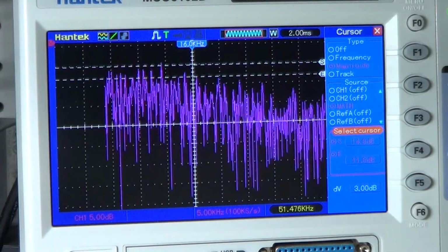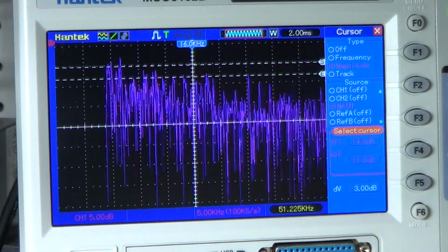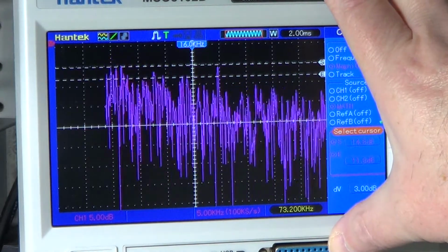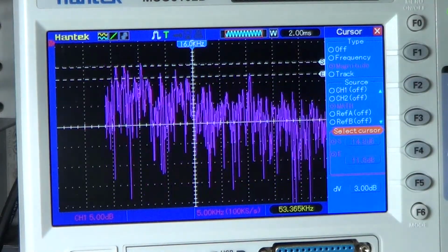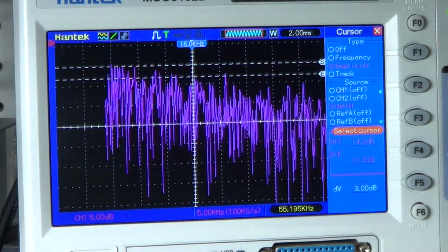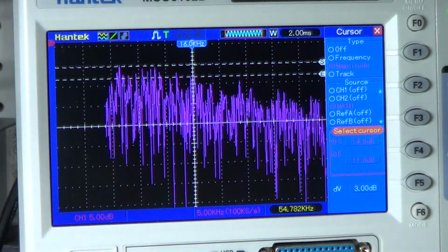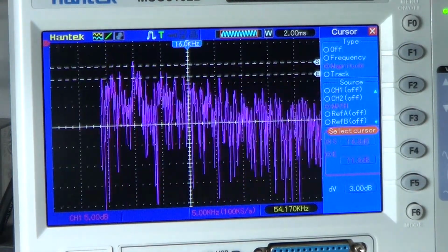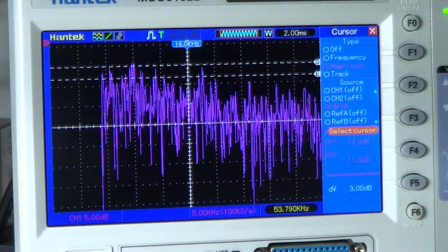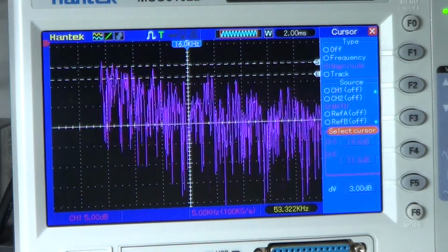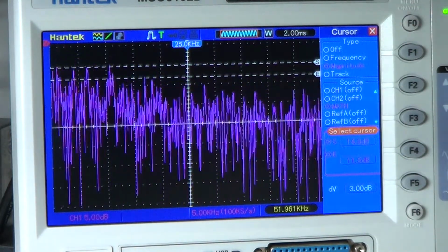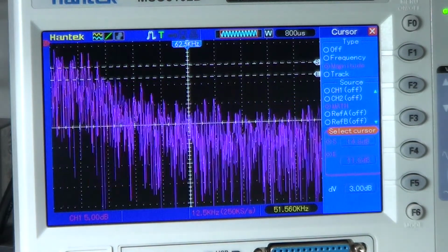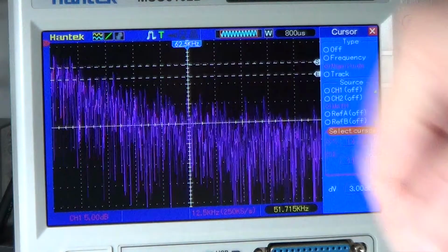So here is how you measure the cutoff frequency of a filter using an oscilloscope with capability of showing images in the domain of frequency. If you have an actual spectrum analyzer instead of an oscilloscope like this, it will work basically the same way. The other thing I want to show you how to measure is how fast the amplitude goes down with the increase of the frequency. To do that, let's bring the image over here. Let's change the scale a little bit and increase the frequency. There we go. So we can better see the descending shape.